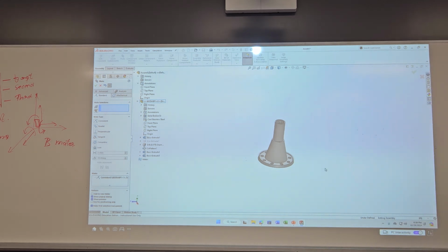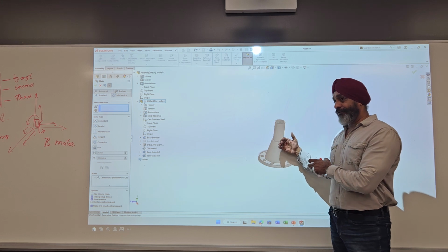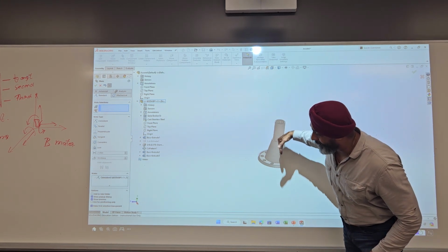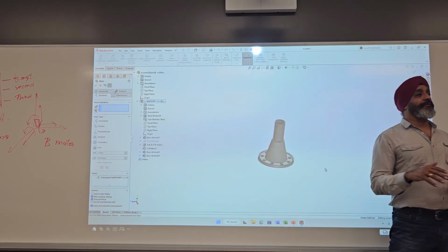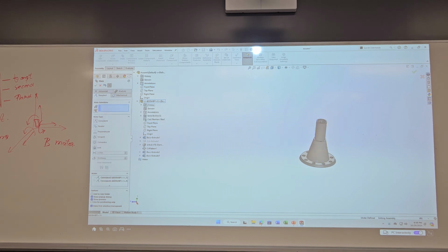So really, there's no binding on which way it needs to be locked in. What is that, Z and what plane? X plane. But I still want to lock it completely, so let's make the planes to the planes. Front plane of the assembly to the front plane of the part, and then right plane of the assembly to the right plane of the base part. Leave them all coincident.